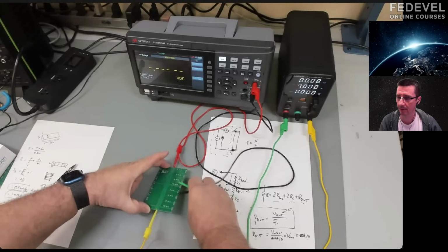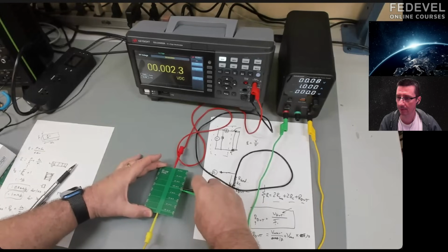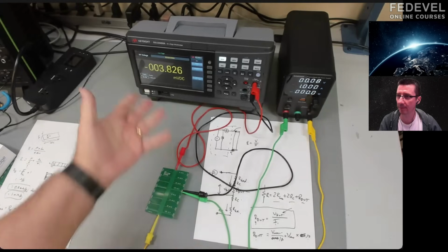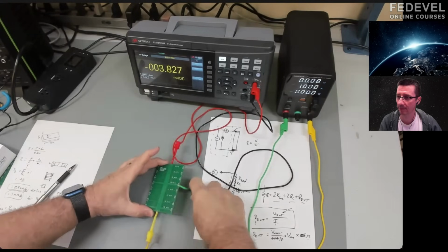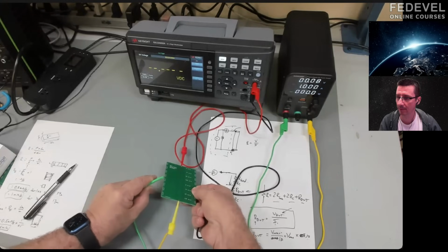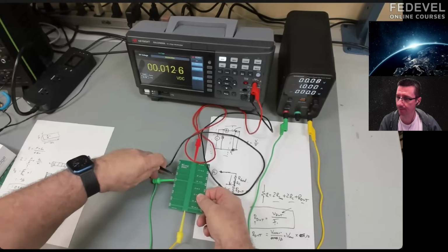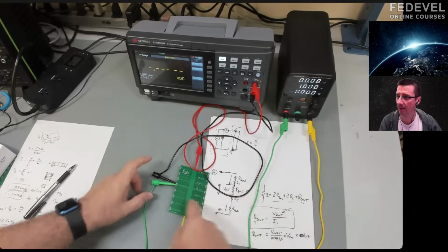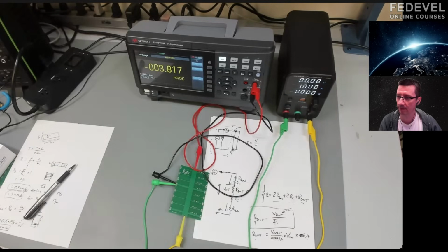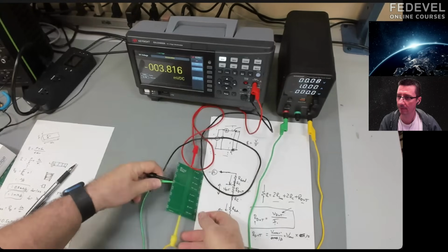Let's go over to the other side. And first, let's just redo this measurement just to see how reproducible it is, because it shouldn't depend on the contact resistance or anything else. We're at 1 amp. There's 3.8 milliohms, right? Very consistent. Let's just go to the other side, and we will do the same connection here. And this measurement, because it is forcing the current, is independent of the wire resistance and the contact resistance. It is the same current. We're measuring that voltage, look at 3.8 milliohms. So same resistance for that trace, very consistent.